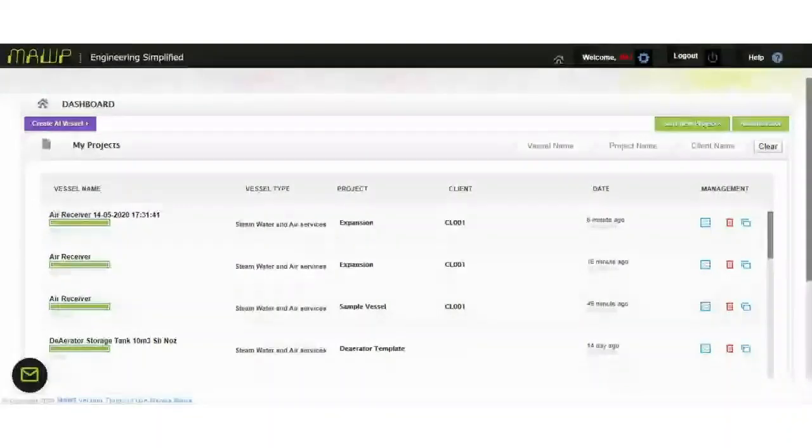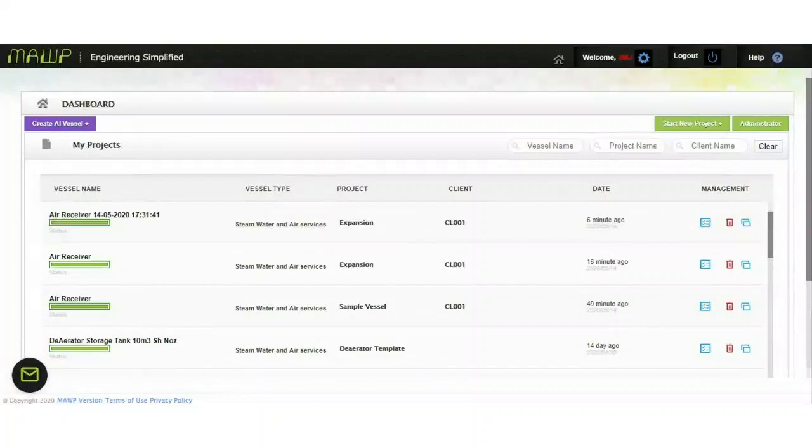Foundation bolt sizes, yeah. The question is whether there's load data for the vessel and foundation bolt sizes. Right now we have the basic saddle design, and you can specify the bolt sizes in the saddle, but the software at the moment doesn't recommend the bolt size. But the saddle calculation will be done with the given bolt sizes.